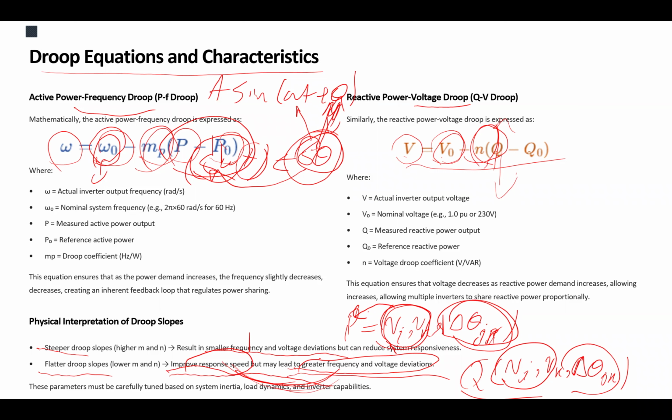No, that's not the case, because this also relates to the grid that you are working with. You have to simulate what's going to happen when your inverter reacts to the network that it is connected to. And while limiting these values, it would define its own specific M and N. Make sense? So it's an optimization process.